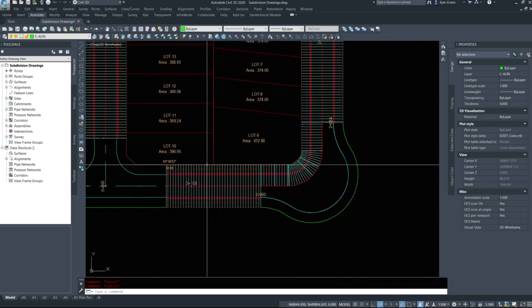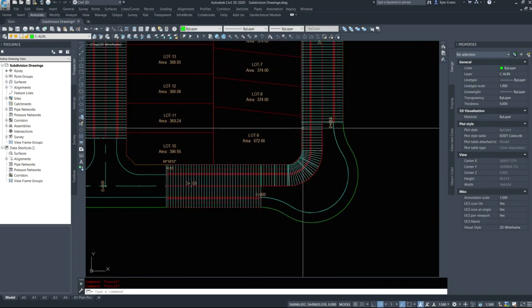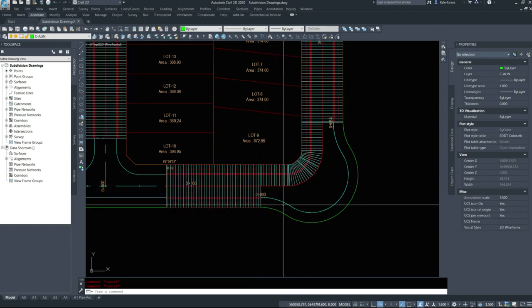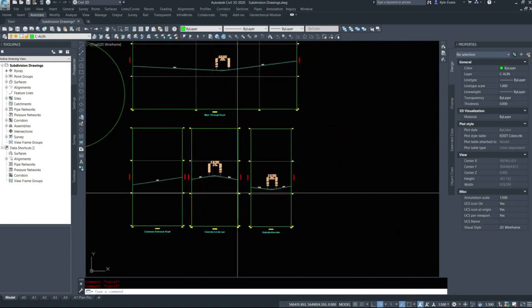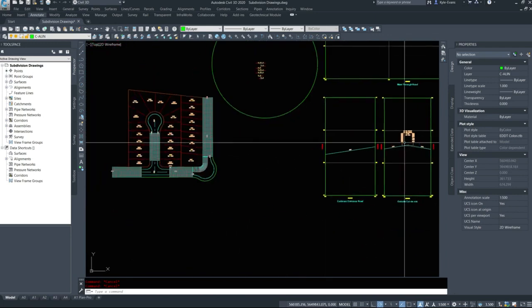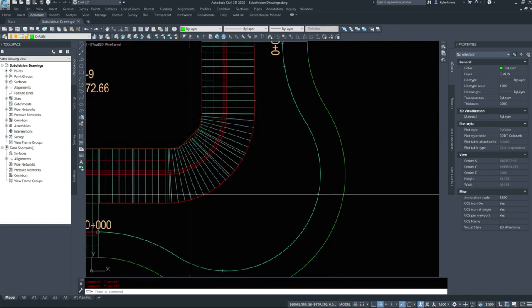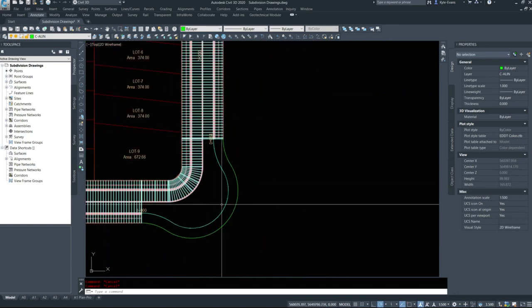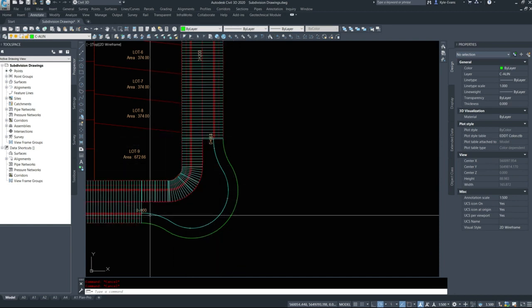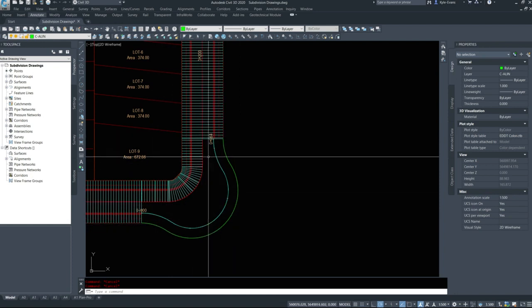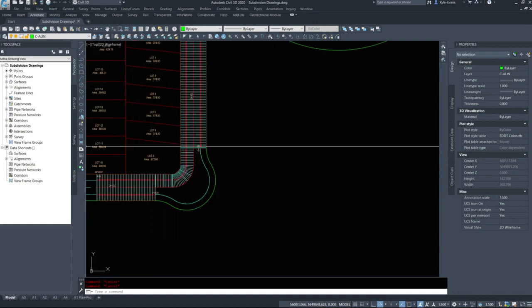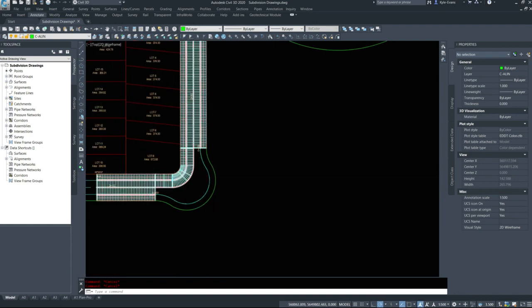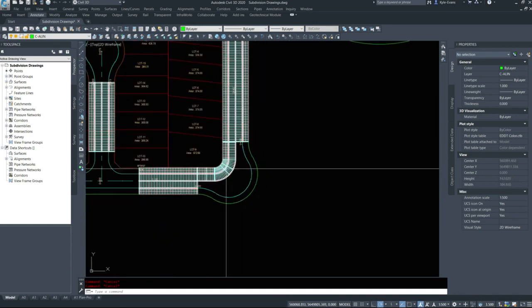I've got residential road main. Then I have residential road left side only. When we're building a knuckle, we need the elevation from the knuckle itself, so this one here, and we need to target the elevation back from the center line. So because we're going to stretch the alignment or stretch the assembly, the corridor, we don't build anything in this location. We do, however, have to build the left side of the road. When I go and build that knuckle, we can turn this off, the left side piece, and you can see what happens there.